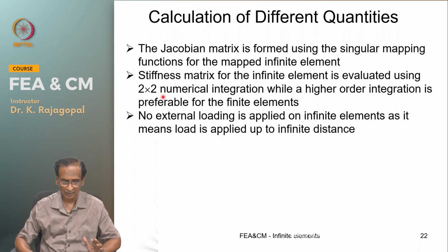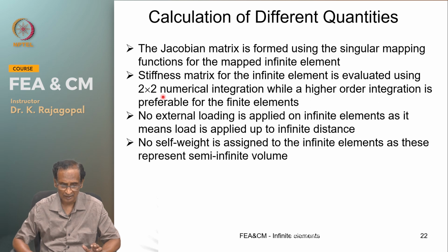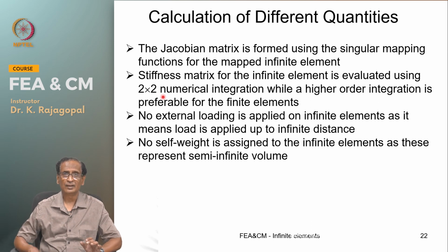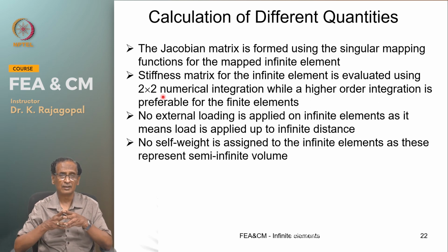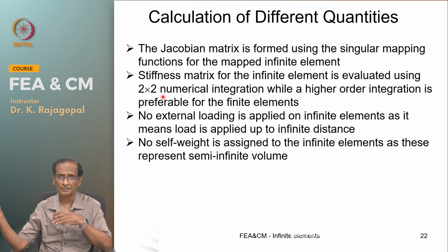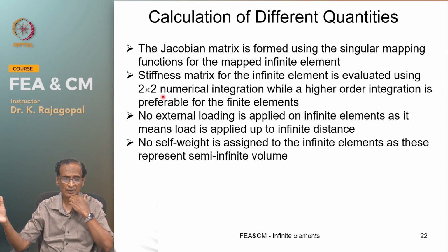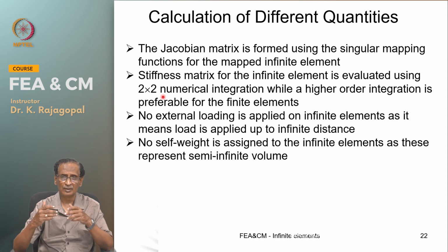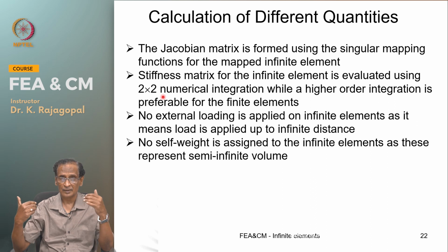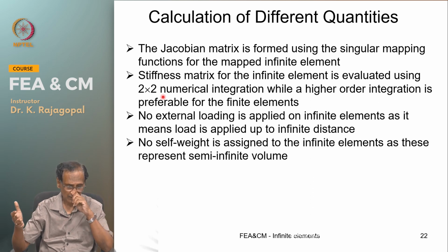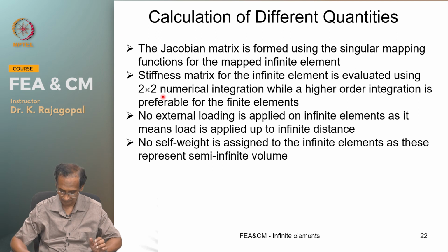Similarly, self weight should not be assigned to the infinite elements, because these infinite elements represent infinite soil volume, and if you define any unit weight, you will see some peculiar results, because your gravity forces will be so high that your displacements will be very, very large.